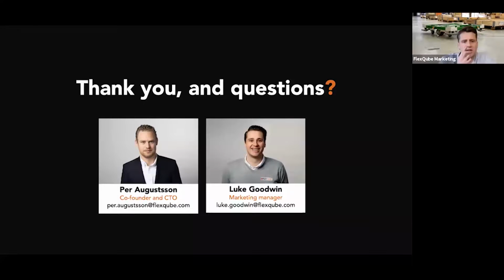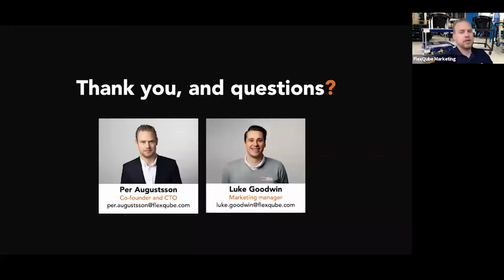I have another question here from Isolano. What is the maintenance on the eQart? Yeah, it's not very much maintenance. We are using brushless motors, so it's more or less about cleaning, looking after the safety scanners, looking after the mechanical design and so on, checking for loose bolts on a yearly basis, I would say.